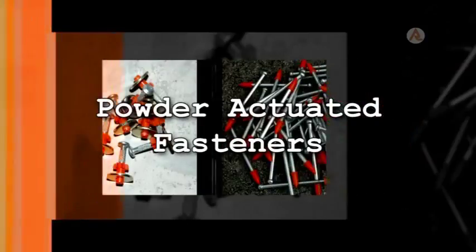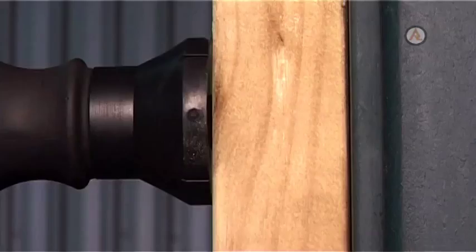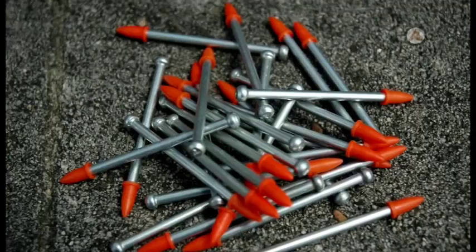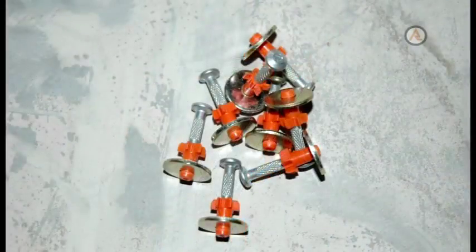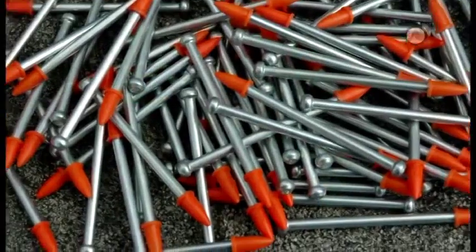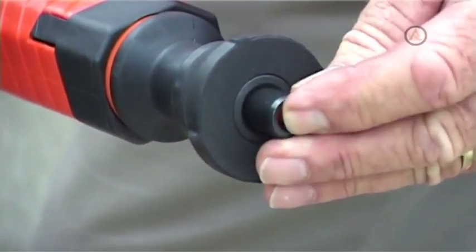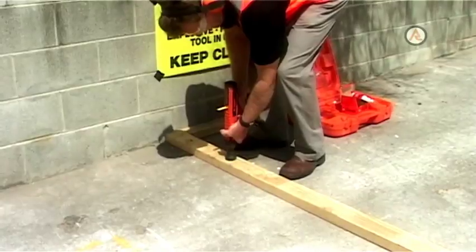Powder actuated fasteners. The primary objective of powder actuated fastening tools is to safely and efficiently set a fastener firmly and securely into a specific material or materials. The fasteners are specifically designed to be used with these types of tools, and a wide range of pins and studs are available to suit many applications. All fasteners include a plastic guidance tip. This tip centers the fastener in the barrel and ensures that the fastener remains in the correct position until being fired.